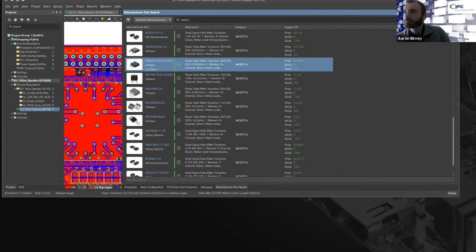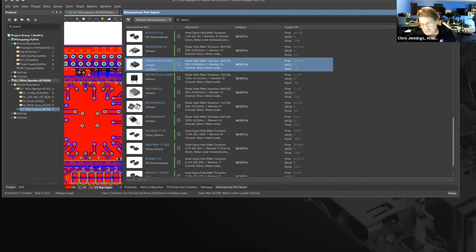Now, there's exceptions, obviously. Some parts are just what you need, and so it's worth it. But again, it takes time, and there's risk, because if you create a footprint that's not right, then you may not be able to fabricate the board. So that's a critical decision point. Normally what happens, like I said, is the PCB engineer has to deal with whatever they've been given. That doesn't mean they won't come back and say, we can't find this footprint anywhere. Are you sure you want us to try to create it? There's risk involved, or it's going to be a delay. Is there another part that we can use? Sometimes there is, not always, but sometimes there is.